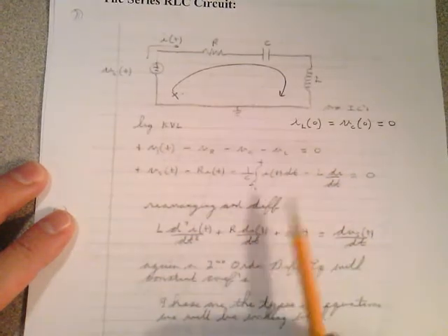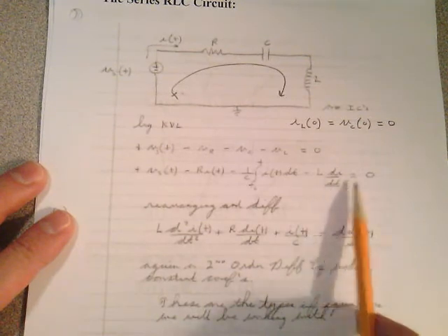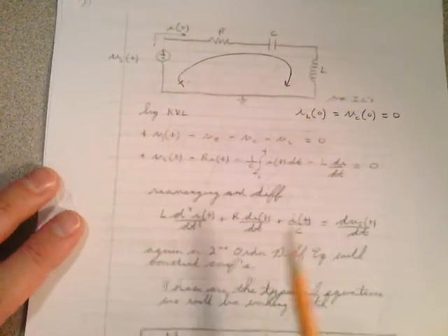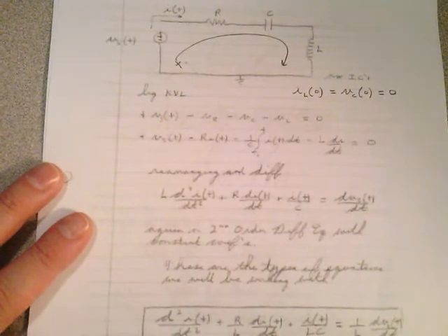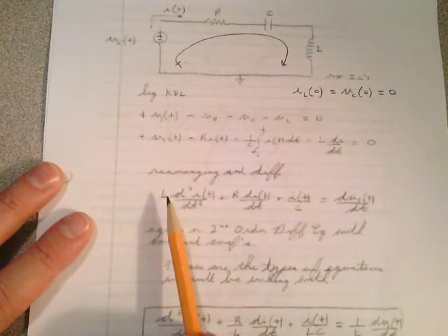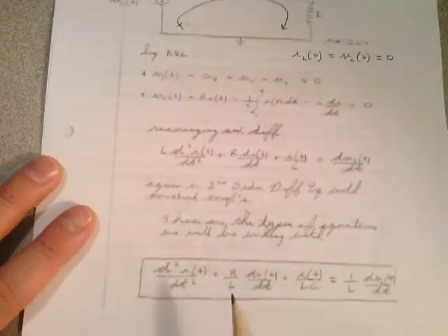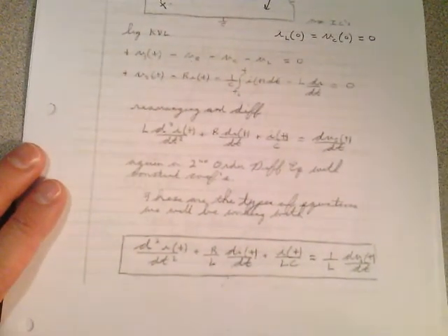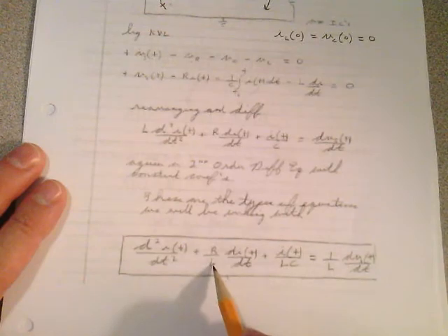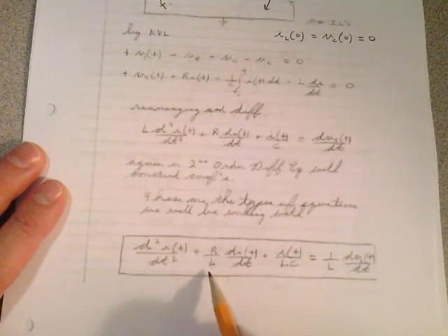And the voltage across the inductor is L di/dt equals 0. Rearranging and differentiating and bringing L down, we get a standard second order linear differential equation with constant coefficients. It yields this equation down here. Notice if we bring this R to the denominator and form a common fraction down there, that's a time constant down there.